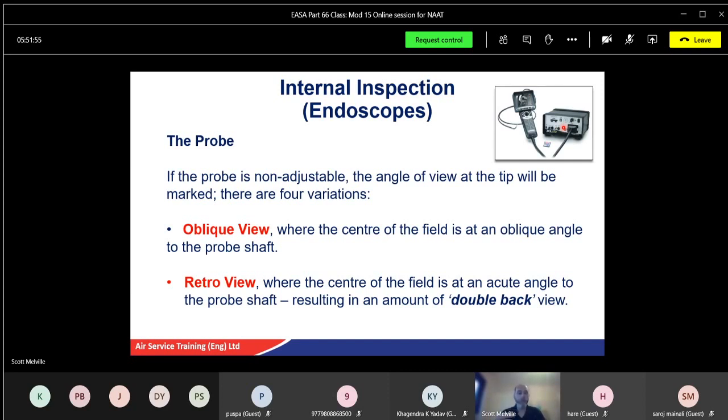Somebody would turn the gearbox to turn the HP, and there'll be another part for the IP shaft as well. The LP shaft, you just spin by hand. But certainly you need to know what you're looking at. The further into the core of the engine, once you're getting closer, you might have to do what we call map a turbine and NGV.